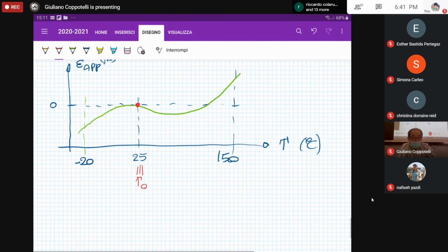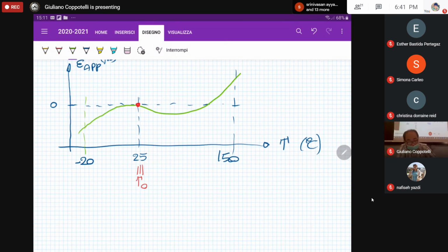Once you know that, you have the compensated strain, let me call it epsilon star, is given by the measured strain, the one that comes straight from your measuring device, compensated by this apparent information.